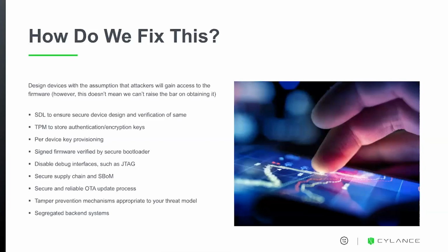Disable debug interfaces in production devices, such as JTAG, UART, SWD, BDM, all of those. What happens is that these are put in place on prototype devices and then left in place on the production run. And those should be removed, and not just the pins or the interfaces, but the pads themselves, because from an attacker perspective, it's only a little bit more work to solder pins onto those pads. So they can't be left in place on the board as well.